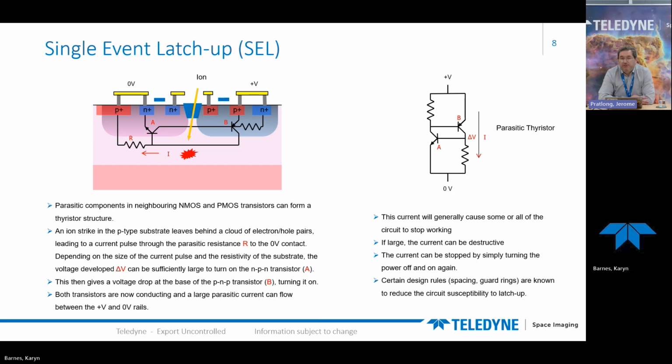There is a positive feedback loop that will apply a great gain on this current, leading to potentially a very high current demand between a supply and the ground, basically creating a short. By doing so, this could be much higher than what the electromigration rules can tolerate within the silicon. And some power supply can be completely broken from the external world, making the device unusable.